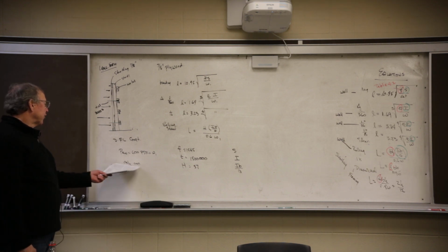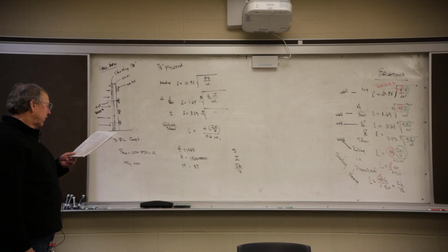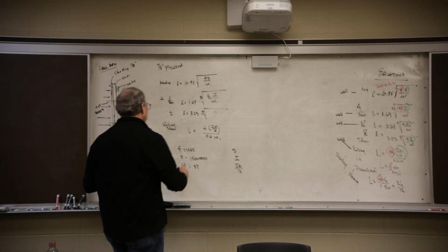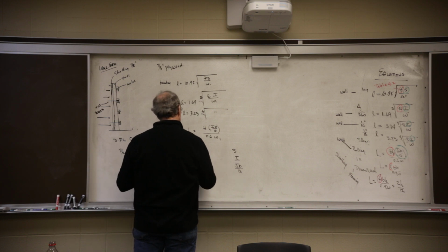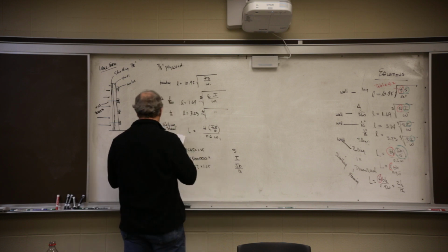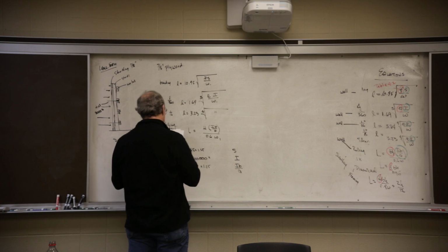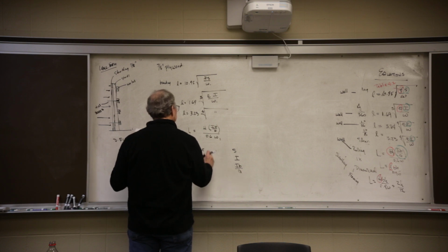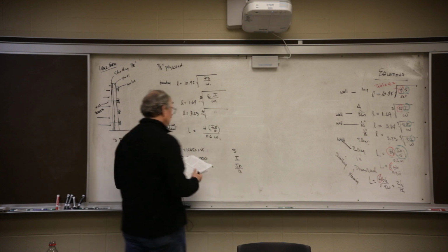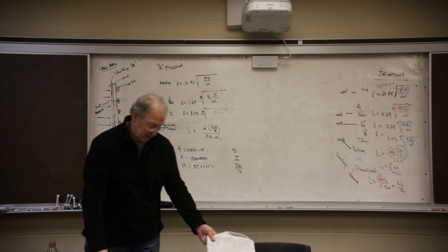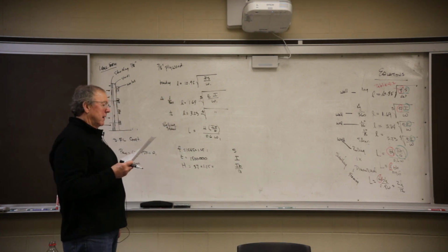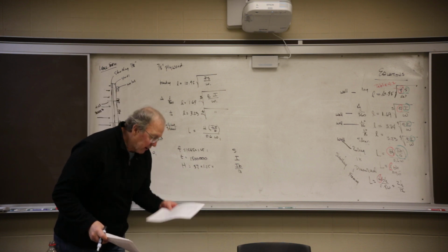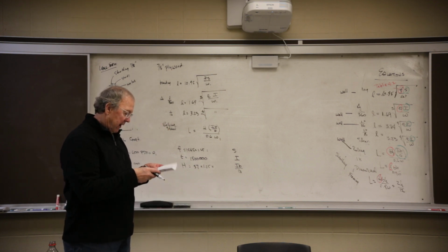But we have to worry about this once only. Once only, increase durations by the following. It says increase the bending stress, increase the horizontal shear stress, and do nothing with this. So that's what they should have done. Let's see if they did. Look at the values for the materials.